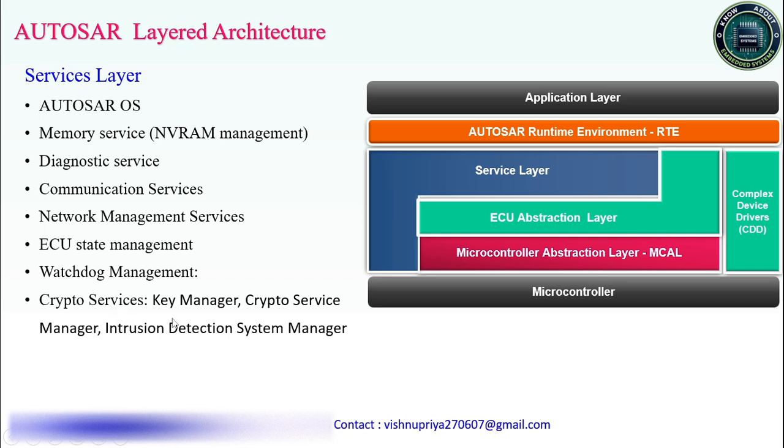The key manager is responsible for managing the private and public keys. The crypto service manager provides the different services offered by the crypto stack. And the intrusion detection system detects if any unauthorized data transmission or unauthorized data reception is happening. So all these things come under the service layer.